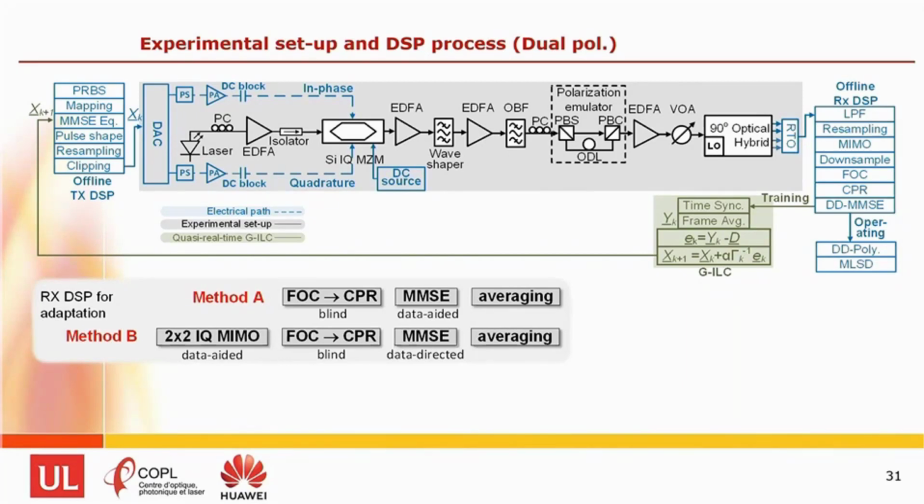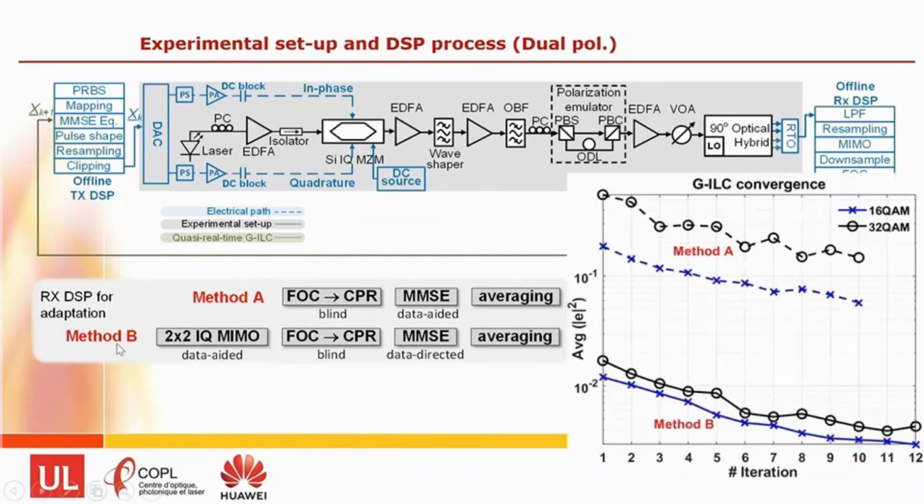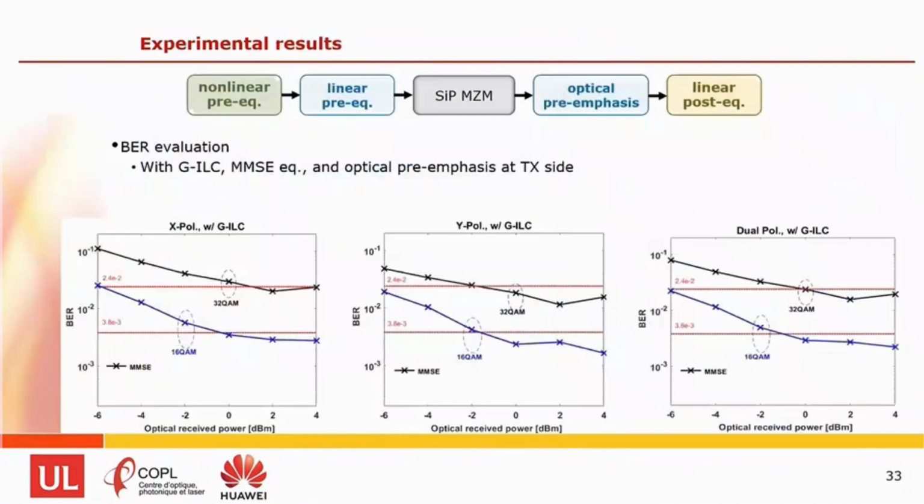The important thing was to do the compensation here at the IQ stage, and of course lots of averaging. And in the end, this was just a much better way to do our convergence. I probably should have done it first on the single polarization, but we were getting decent results without it. But coming up with a better way to allow our quasi-real-time adaptation to have a better view of what nonlinearity remained to be compensated, by doing a better estimate beyond the noise, allowed us to come up with a much lower error in our precompensation.